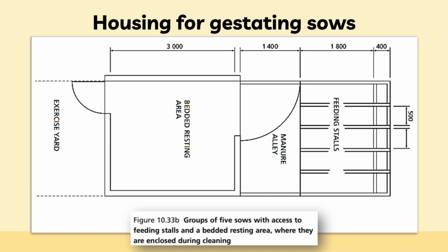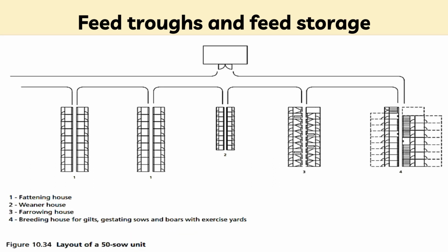Feeding stalls are 50 cm wide, with a lowering bar to prevent interference. A manure alley with gating allows for easy cleaning, with adjustable width for tractor-mounted scrapers. Exercise yards may be feasible behind both types of pens. The spray system benefits all pig categories except very young piglets.